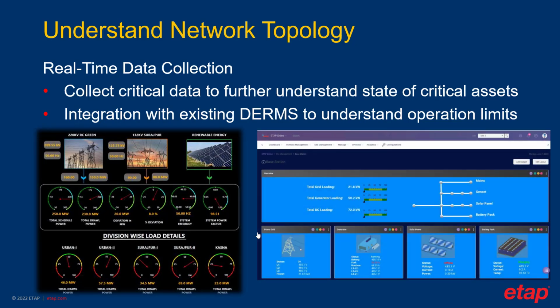This is very important in areas where voltage distortion and low voltage conditions can cause interruption of the internal processes. In this case, the load shed system must understand the voltage support that DERs can supply when performing load shedding. In addition to the digital twin model, the ETAP iDLS offers operator views to facilitate the management and operation of the controller.